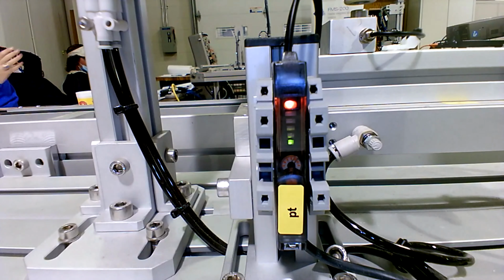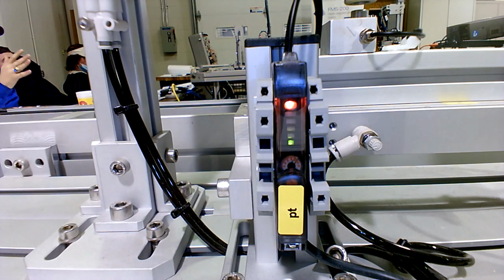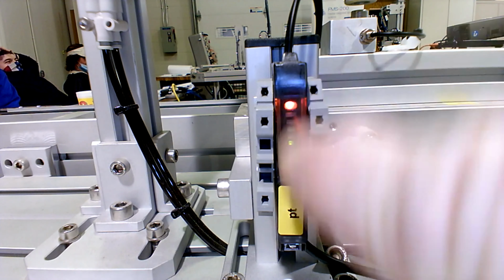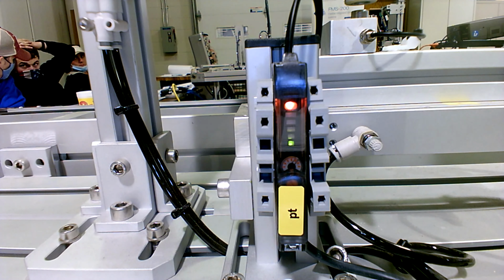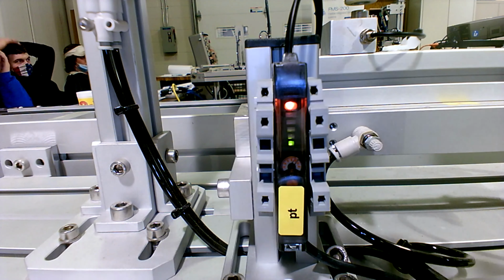The lights changed. So listen, here's what happened. The screw went down in there, it blocked the beam, and then it lost the signal over here. So here's what you have. The PLC is looking to see when the screw drops in there and it loses the fiber optic signal, it knows there's a screw in the hole, okay? That's how it knows. Now let's let it index through and you're going to see that change.